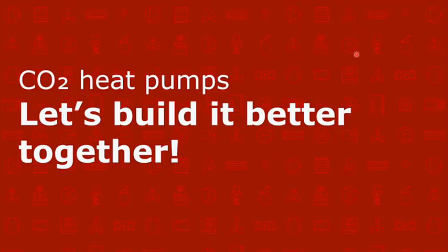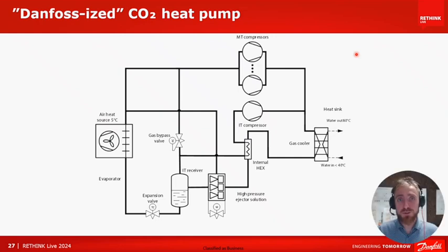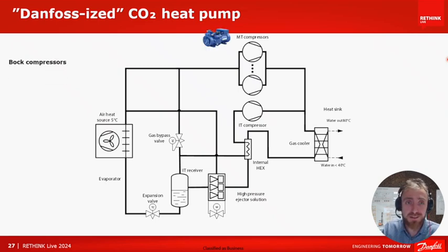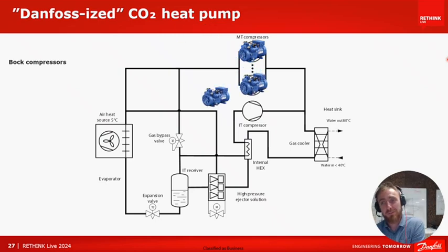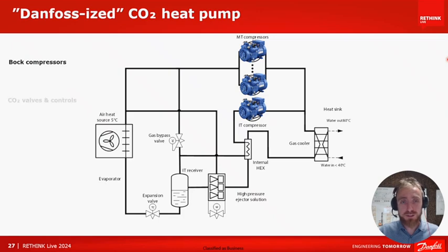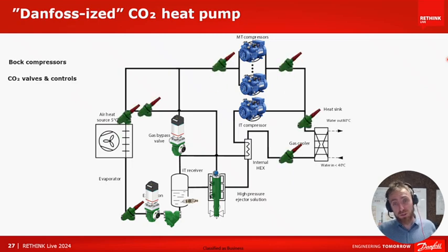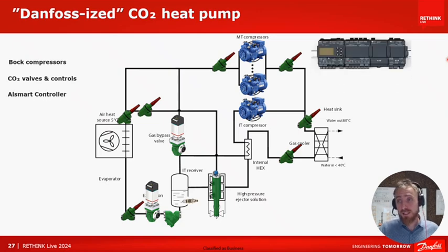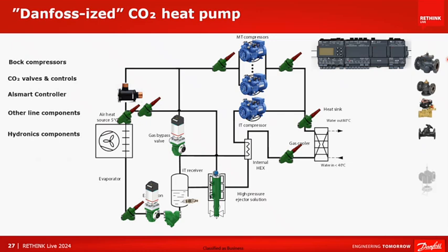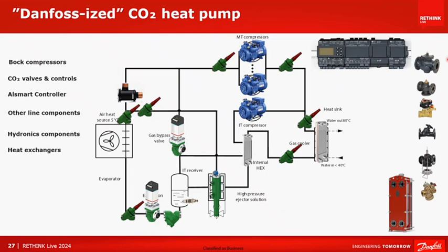Let's wrap it up. We in Danfoss would really like to support the decarbonization journey of the industry in North America. And we really would like to support with our experience with CO2. You saw, layout is one thing, but components and adequate selection, they can really make a difference on system level. So compressors for transcritical CO2, valves, precise control, sensors, defining also good superheat, proper controller of the entire ecosystem, many other line components, also control on the hydronic side, heat exchangers, both CO2 up to certain size and water to water.